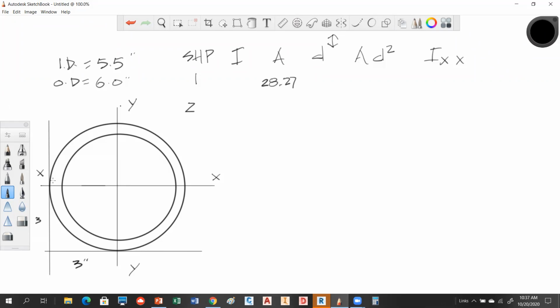All right, so for the shape moment of inertia, if you go back to chart 7.1 on page 218, notice for the moment of inertia, it's just pi r to the 4th divided by 4. Okay, so we have 6 to the 4th times pi divided by 4. You guys check this. My calculator doesn't do that really easily, so I just want to see. I got 1017.888. Verify that for me, will you? That's what I'm getting.